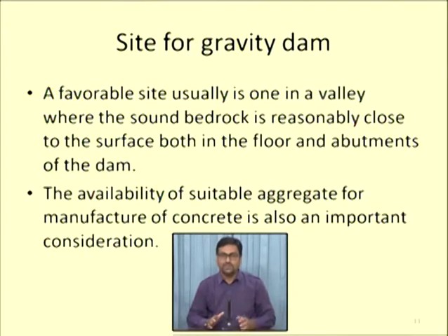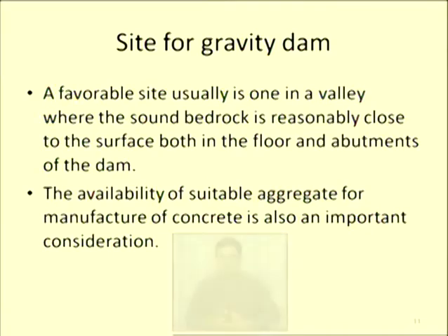So a favorable site usually is one in a valley, that is a river valley, where the sound bedrock is reasonably close to the surface, topographical surface or earth surface, both in the floor and abutments of the dam. Floor, that is the bed of the channel, and abutments means the sides of the valley which can hold the load of the concrete dam.